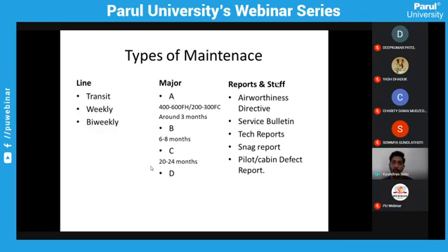Now, what is a service bulletin? Okay, fine. DGCA has said to change it, but how to change it? What to replace it with? You can't just bring a bolt or screw or nail from a shop outside and fix it, right? You can't do that. You need some specifications. You have to change it with an MS or NAS part, some 650 something. The number will be there. You have to remove this particular bolt and replace it with this particular bolt. There is a specification to that.